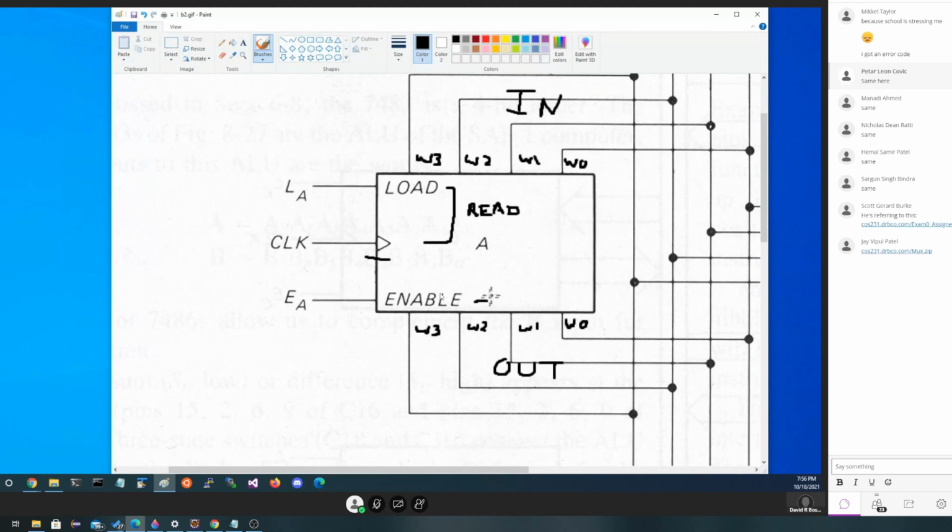If we're going to write to the bus, we must have an enable signal. And our outputs must be tri-stated, meaning that we can appear to not be here to somebody if we're not the person who has been elected to speak on this particular clock cycle.